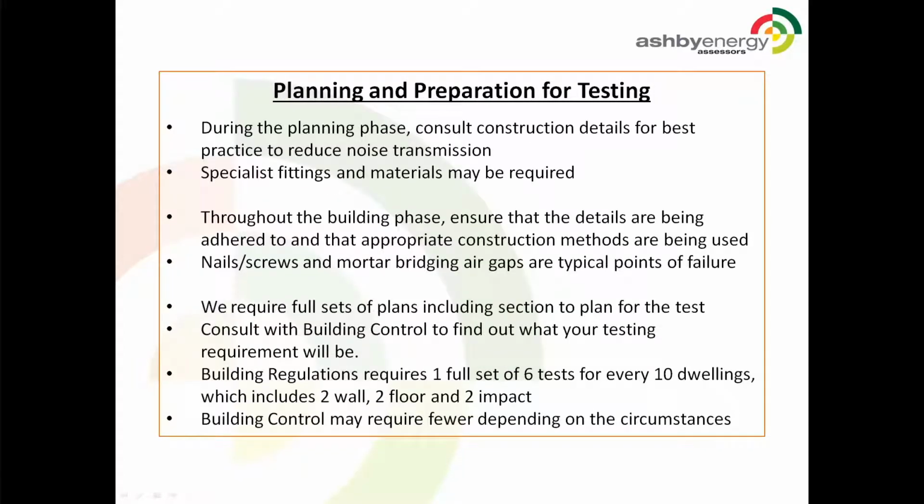Planning and preparation for testing. It is best during the planning phase to consult construction details for best practice to reduce noise transmission. Bear in mind specialist fittings and materials may be required to reach target noise reduction. Throughout the building phase, ensure that building details are being adhered to and that appropriate construction methods are being used. It is advisable to employ builders who have prior experience with the building details being used, as they pertain to noise transmission reduction. Nails, screws, and mortar bridging air gaps are typical points of failure, allowing direct paths of noise transmission through the partition or floor.